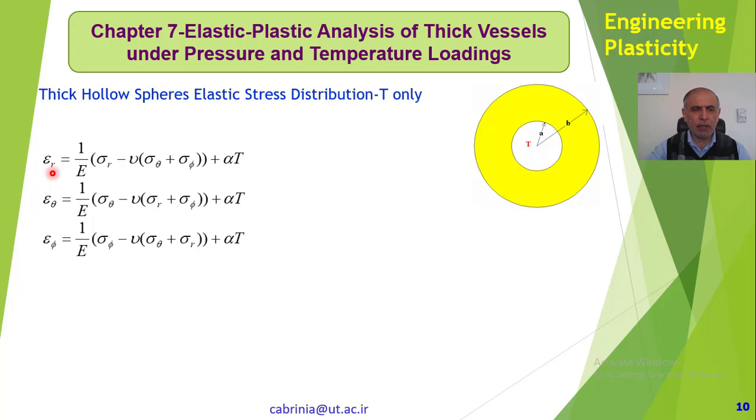and therefore we get some strains due to those stresses. So strain in the radial direction, we use the elastic relationship. These are the stresses due to the temperature difference. Also we get an expansion, obviously, which is to do with the coefficient of expansion, alpha times T. That gives the displacement, so gives the strain. So the strain in different directions, we get different values of stresses.